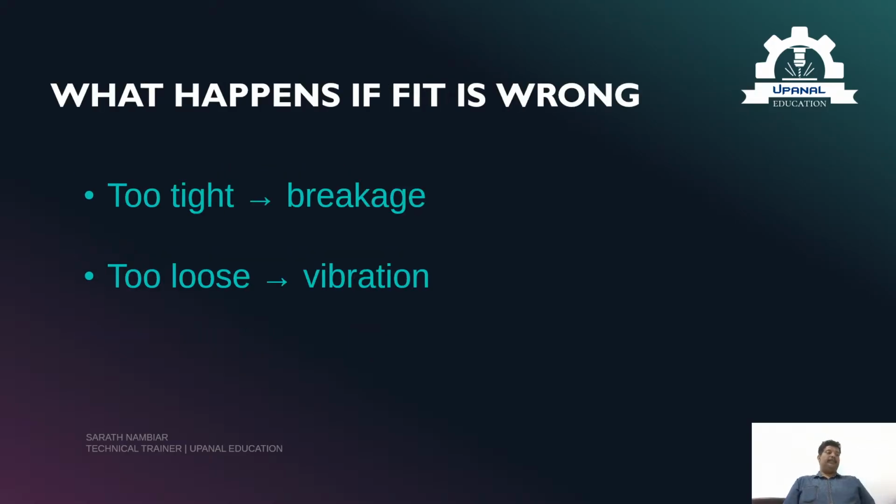Choosing the wrong fit can cause serious problems. If the fit is too tight, parts may not assemble, excess force may crack the component, and friction and heat increase. If the fit is too loose, the parts start vibrating, noise increases, wear happens quickly, and the machine life reduces. So correct fit selection is very important for performance, safety, and durability.